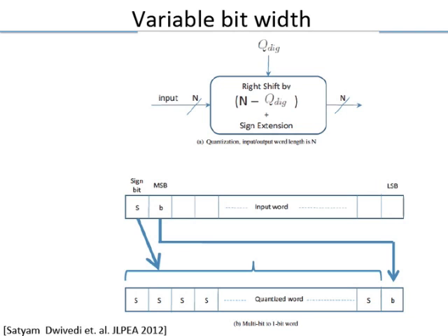Now, the quantization error you can tolerate may be different at runtime, when you are actually using the system. Maybe it's a DSP, and for some application I just need 4 bits, for some other application I need 8 bits, and for some I need 16 bits. Different applications need different resolutions because they are dealing with different signals and doing different things. When you design this kind of a chip, you design for the highest resolution. You'll say, okay, I know I need 16 bits. But when I don't need all the 16 bits, if I still use 16 bits, I'm just wasting power.